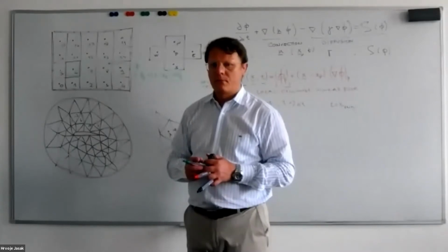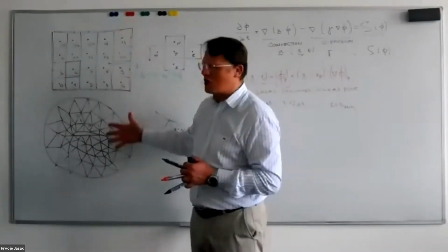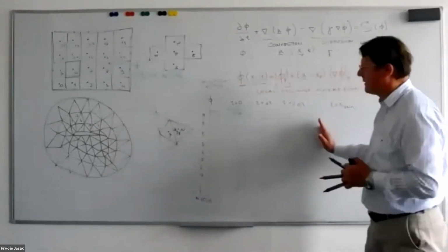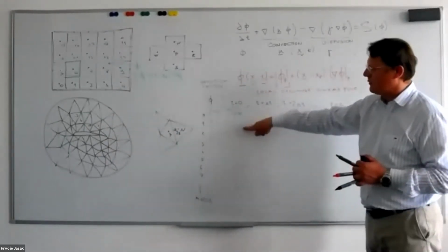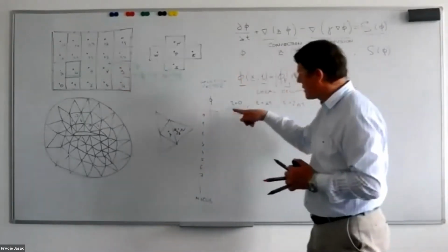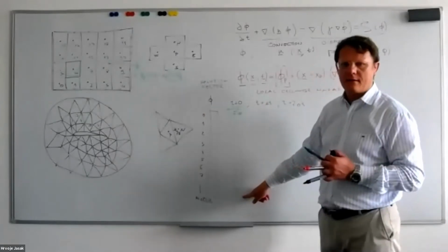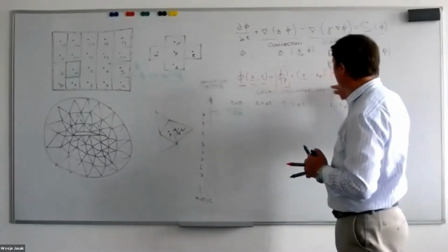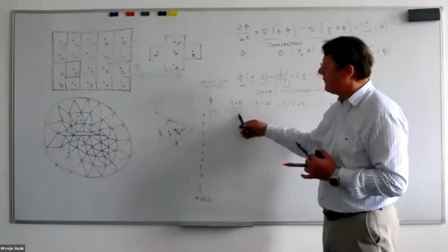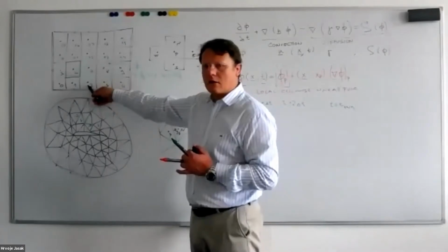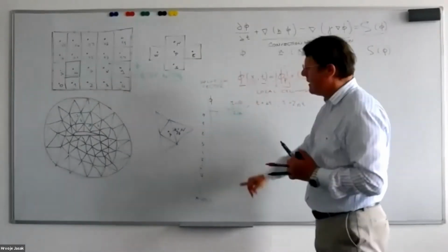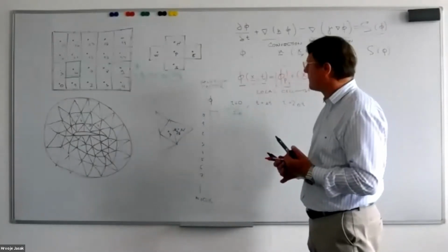boundary condition. So this describes the machinery of storing the solution, advancing it in time, and relating the solution vector with the location in space. If I just give you a set of values of phi, you would not be able to perform this linear interpolation because each value needs to be associated with the location of the cell center of the appropriate cell by its ordering in the list.